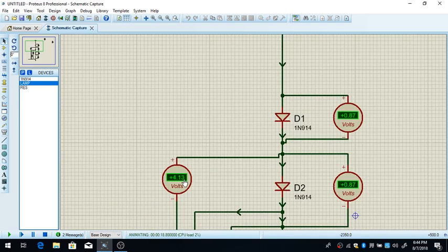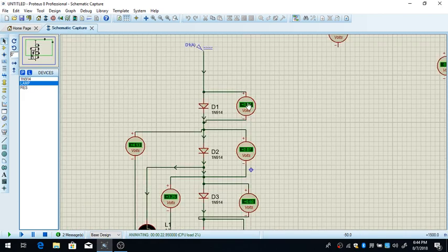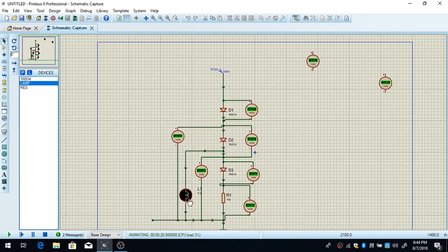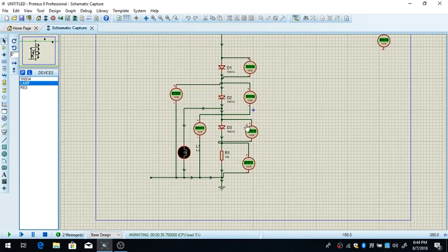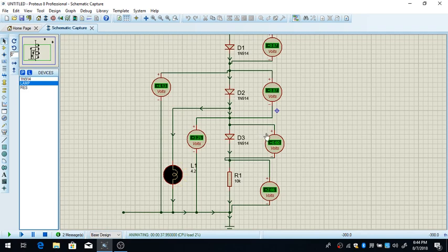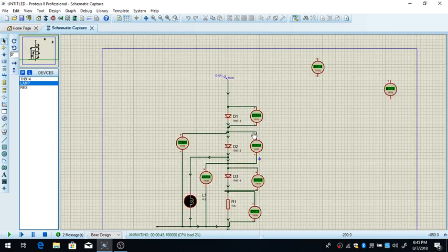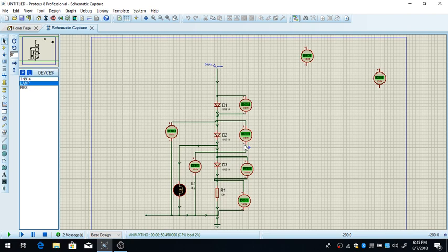So now we have here 4.13. Then the voltage drops on this diode 0.87, and here we have 0.60. So it varies a little bit with various types of lamps, with internal resistance and so on, but the main part is the same, so not to worry about. Here we also still have 0.6. We have a little bit larger voltage dropout. So it isn't a good application, but it shows you something about these diodes.